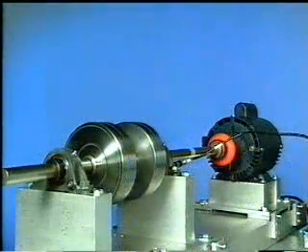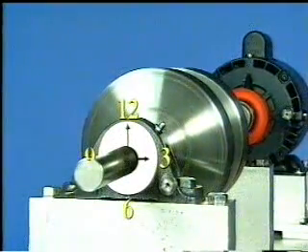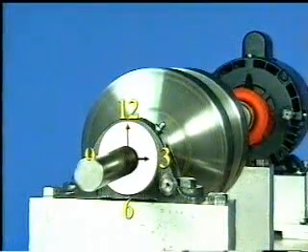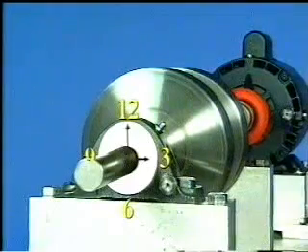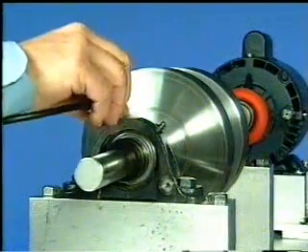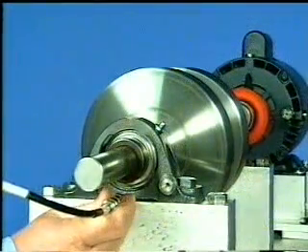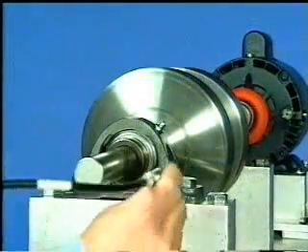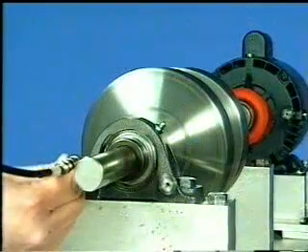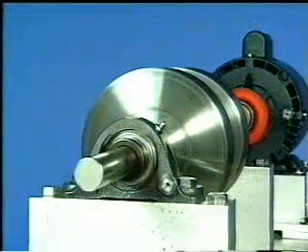Four other axial measurements should be made. Assuming a clock face over the end of the bearing or machine, the measurements should be made at 12 o'clock, 3 o'clock, 6 o'clock, and 9 o'clock positions. A cocked bearing will exhibit approximately a 180-degree difference from the 12 o'clock position to the 6 o'clock position. A 180-degree phase shift will also be present from the 3 o'clock position to the 9 o'clock position. Again, these measurements are normally within 30 degrees.